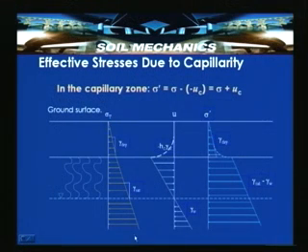Here sigma T is the total stress distribution with depth, and here is the gamma W Hc. This is explained here. When the soil undergoes partial saturation, gradually reducing to a dry condition here, then we have minus gamma W Hc, which is not clearly shown here, and then it reduces to 0 here, and gamma W times H, then gamma W H.